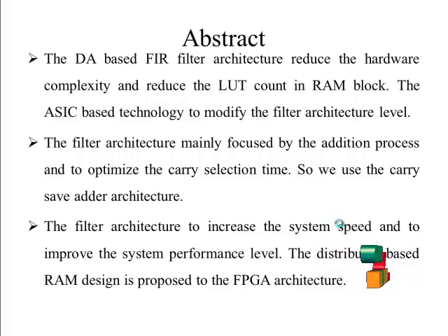The computational complexity and the reconfiguration time of the FIR filter increase with the filter order and the type of arithmetic used. As multipliers consume more power in multiply and accumulate, that is MAC operations, several multiplier-less schemes have been proposed in the literature. Distributed arithmetic is one of the multiplier-less techniques which uses memories.